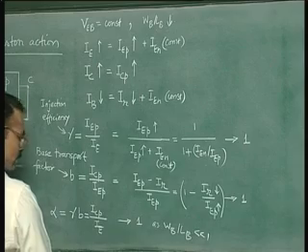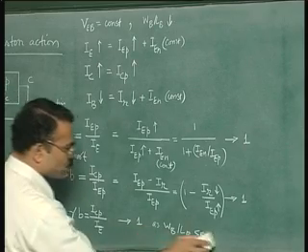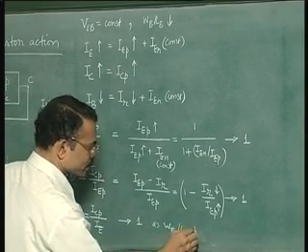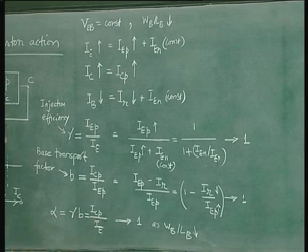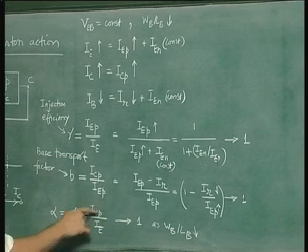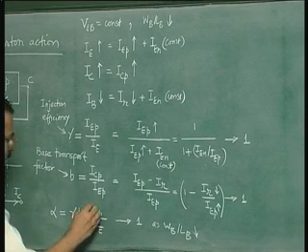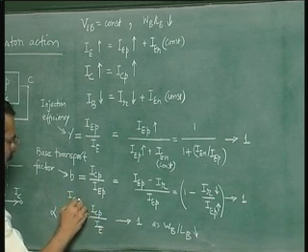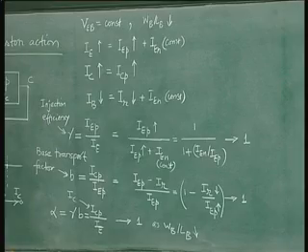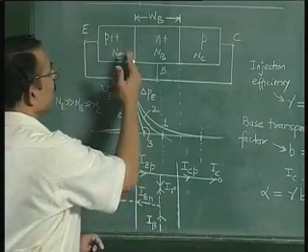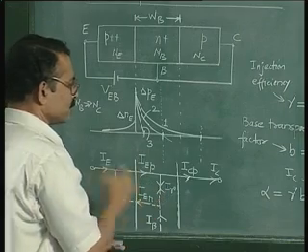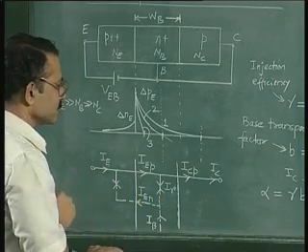So as WB by LB reduces, this alpha of the transistor tends to 1, and this ICP by IE is nothing but IC by IE. So this quantity is IC for this particular case. So the transfer of current from emitter to collector is almost complete for these conditions.